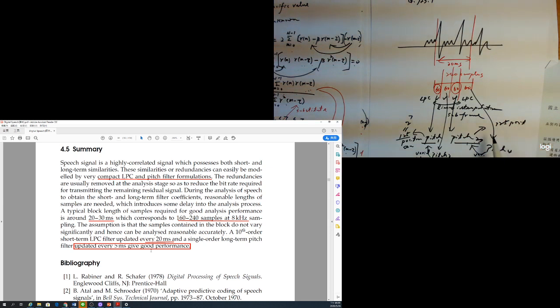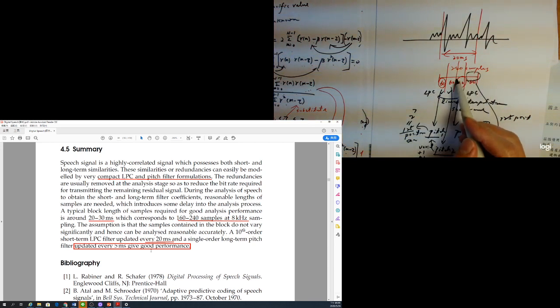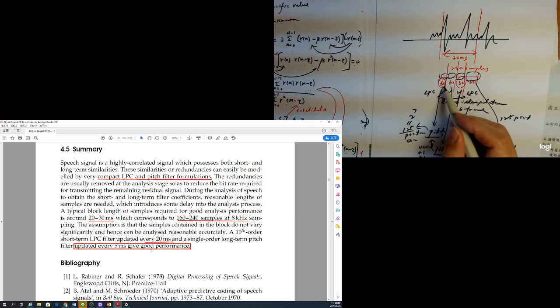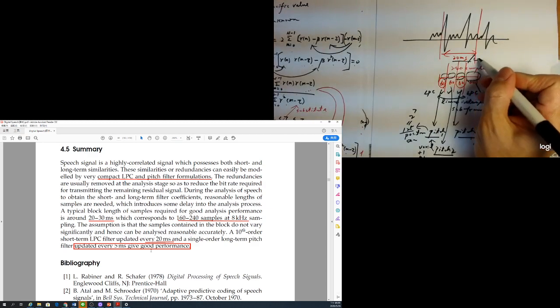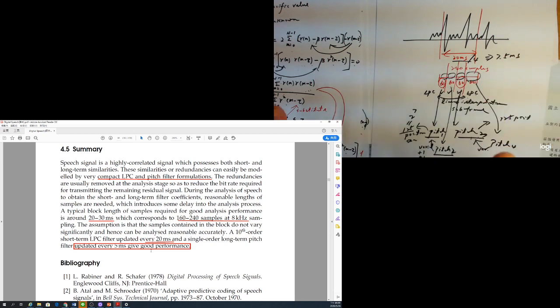So you can see from the standard, most of them try to keep some LPC with linear interpolations. They base it on the subframe to calculate, and also pitch. So they have some variation according to the subframe. Most of them are 60 samples. So this one divided by 4 could be 7.5 milliseconds. There is a little bit of change in their speech frame.